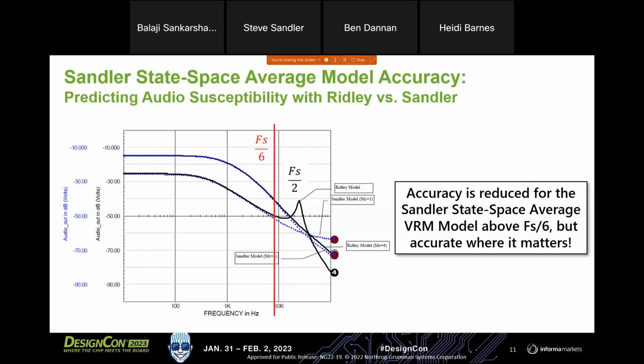What we're missing is the inner current loop stability. And that actually was the main purpose of Ridley's thesis, to show why it is that we ended up with a subharmonic oscillation in current mode control. The problem is that inner current loop resonance only occurs in continuous conduction mode, not discontinuous conduction mode.